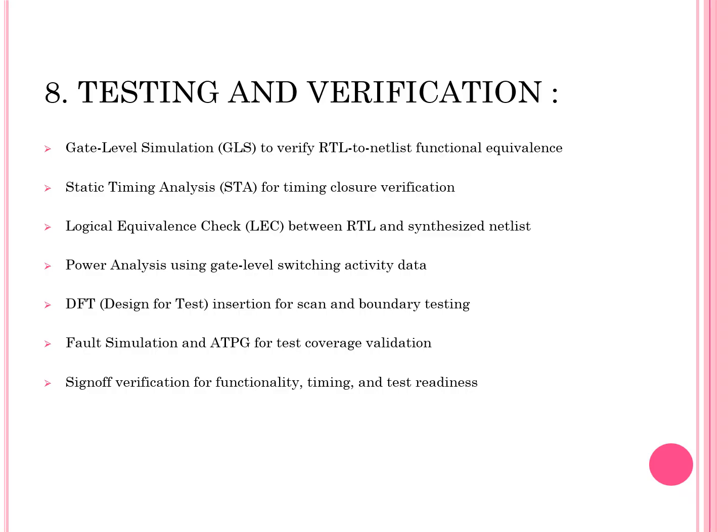Next is static timing analysis, which ensures that all timing paths meet setup and hold time requirements for proper operation. We perform a logical equivalence check to confirm that there is no mismatch between the RTL and the synthesized netlist.